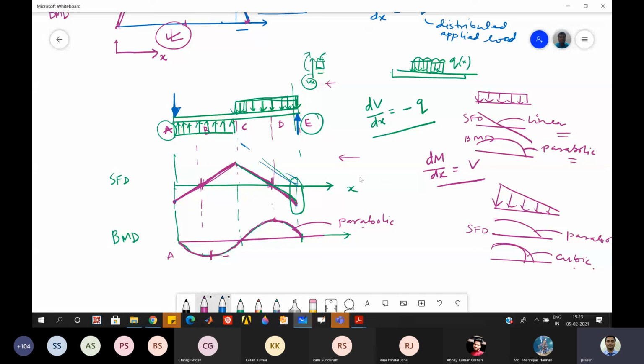So this way you can see I can replace these forces by equivalent boundary conditions. You can put a roller support here and a pin joint at A. So the loading can be something like this. I have a roller support here, and there is some load from bottom to top.